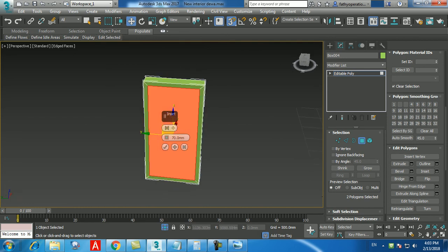Because when you have different segments like cabinets, then you will do bipolygon. Here, if we selected both of them, still it's a group only. No bipolygon. Here, even if you do bipolygon, nothing will happen. Both is the same here. Same inset, yes. Green tick mark to finish it. Edit poly. Click on the black box near inset and type 70 and green tick mark to finish.